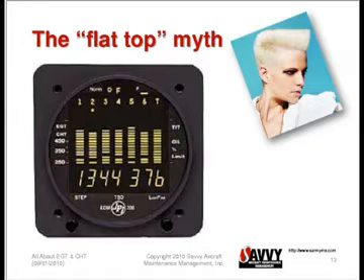Again, the instrument manufacturers tend to reinforce this myth by having the instruments display the differential between the highest and lowest EGT as if it really mattered. On the JPI instruments, this is called Diff, D-I-F-F, and it's one of the numbers that gets displayed on the instrument. I constantly hear from aircraft owners saying, how come my diff is 80 degrees and why can't I get these EGTs closer together? And the answer is